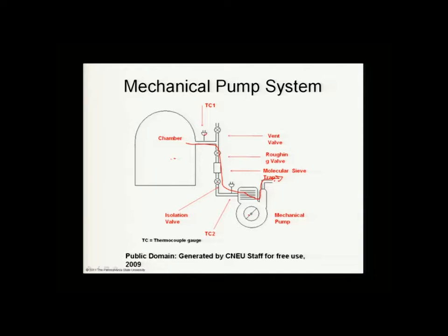So you can see here that you can pump down. You can have gas coming in for some processing. You can be continuously pumping. If that gas is a problem, you might want to have synthetic oil here. Once you do your processing, you can close this valve. This molecular sieve here, by the way, there can be traps here, but a molecular sieve here is to stop the oil from backstreaming. You can isolate this pump. You could then backfill in, say, nitrogen this way.